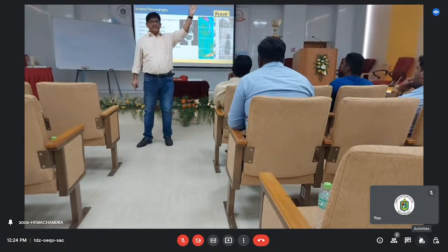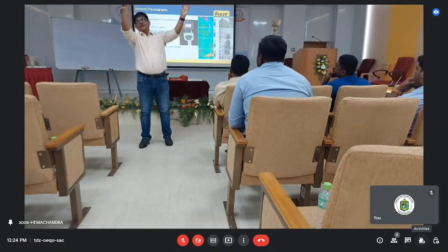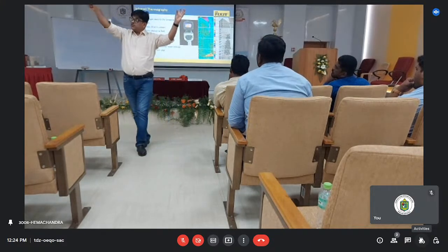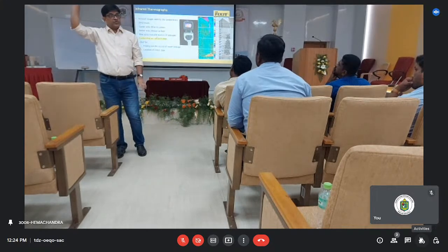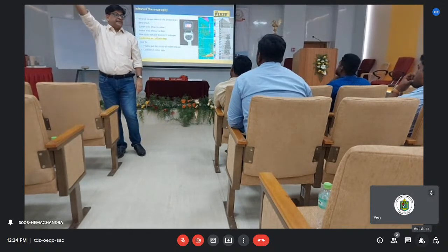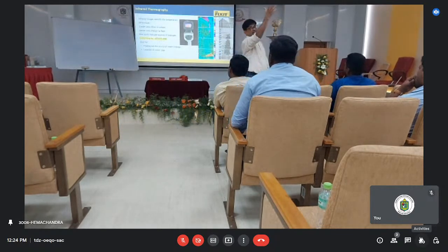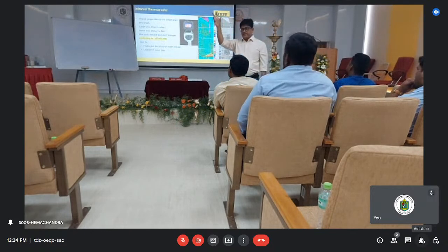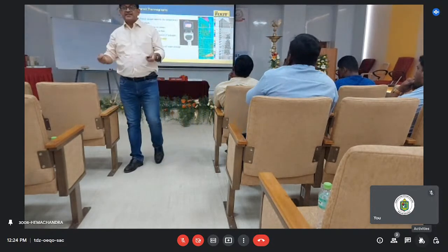Maybe the leakage is shown here. From the entire scanning, we'll understand this is the path the water is taking, and another problem shown there may be the source. So it will give you an indication of where the source is coming from, and you can find out there may be a pipe there. So you have to scan the whole thing through the camera, and then ultimately you can find out the area. It will give you an understanding of how the water travels.